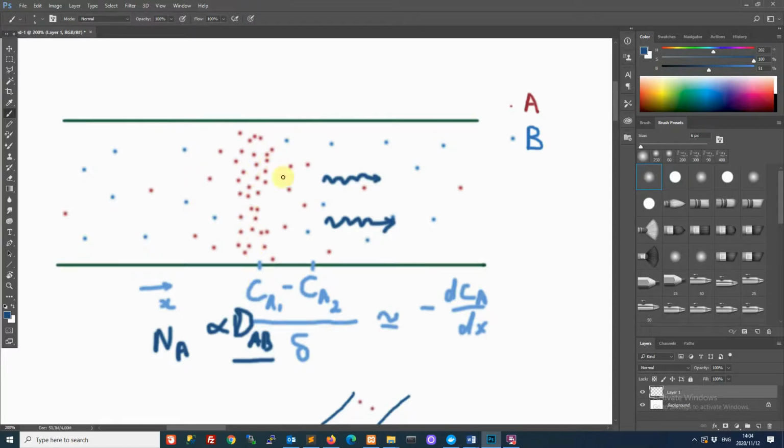Then for gases and liquids, there are different expressions, because in the gas phase, of course, the molecules have far greater intermolecular spaces, and so the nature of the forces influencing the tendency of the molecules to push off is going to differ. So we anticipate that there won't be one unifying model, at least not at the outset, that will describe the diffusivity. But at the same time, the diffusion rate is important enough to us as chemical engineers that we have to become aware of some of the correlations out there for estimating the diffusivity.